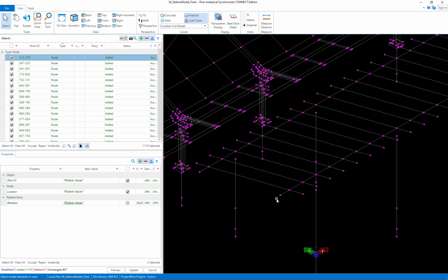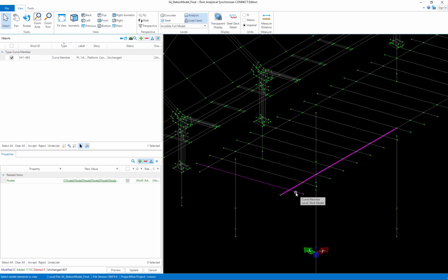It's important that your analytical member lines in your BIM application do intersect to make sure that there is proper connectivity. Here you can see I have my wooden girders. They are supporting my wooden beams. They are all drawn in the same plane. So now when I import this physical model into STAAD.Pro, I know that everything's going to be properly supported.